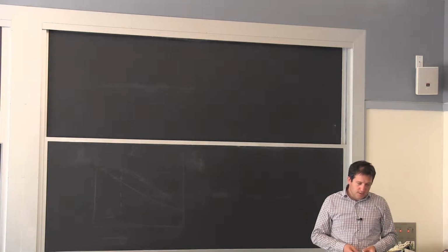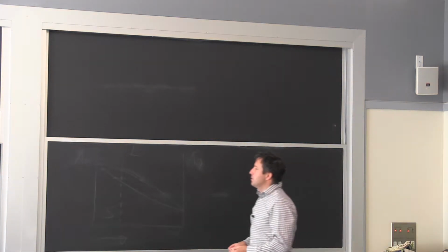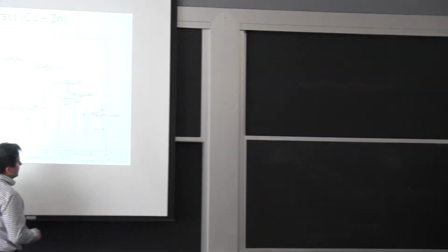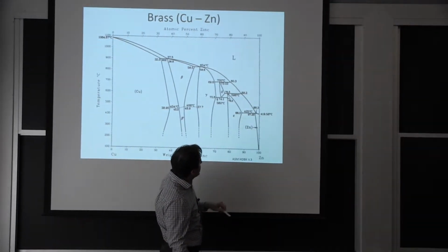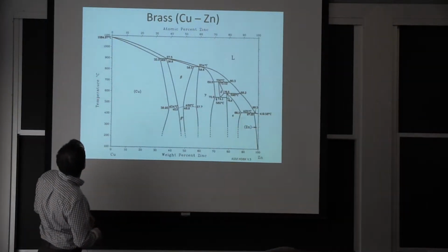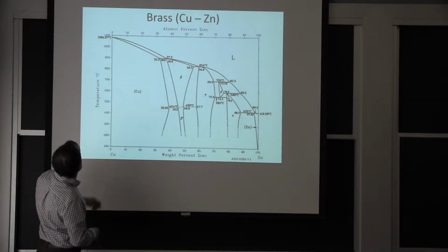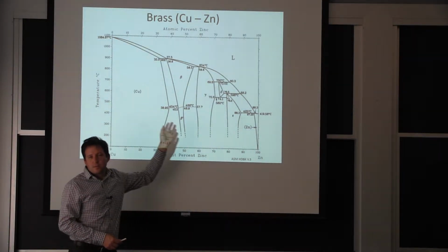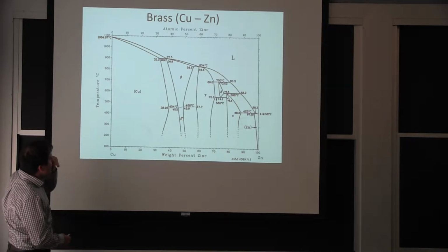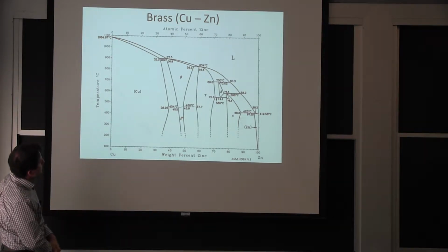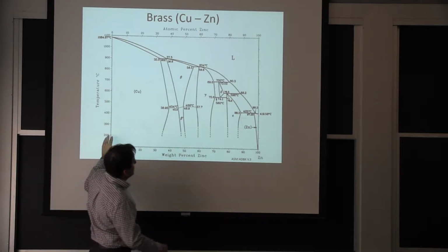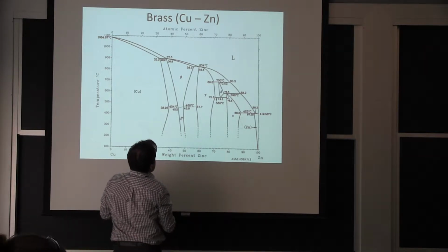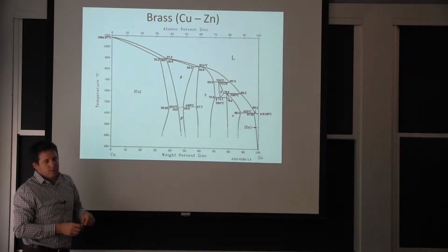So, of course, this phase diagram is probably much more complicated than you'd like to see it, but you can already see some of the common features with what I discussed. Melting point for zinc, it's only around 450. For copper, 1060. So in between, you have a variation. All right? And the only difference from what we've discussed earlier is instead of just having those 2 extremes, now I have steps in between. I have other solid phases that correspond to another arrangement of the crystals.